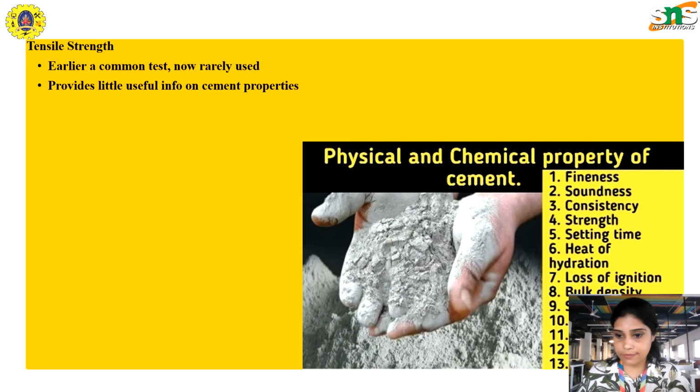necessitating that, to resist tensile stress or tensile force, we infuse steel into it, because steel is the major component that possesses high tensile strength. So the tension will be handled by the steel, and the compression will be handled by the concrete. That forms a perfect formula called RCC, reinforced cement concrete.